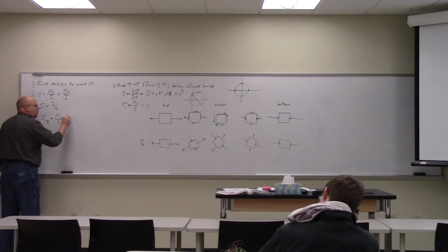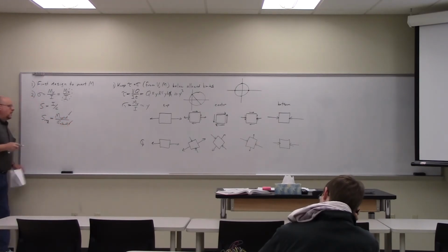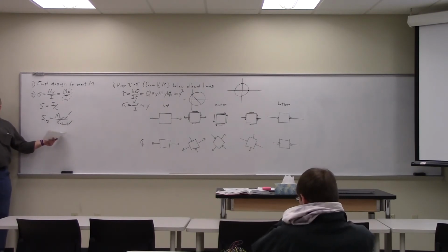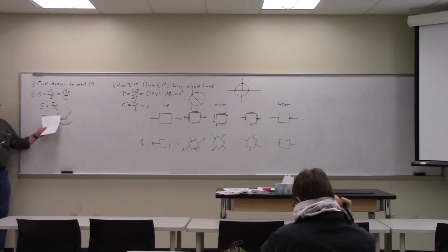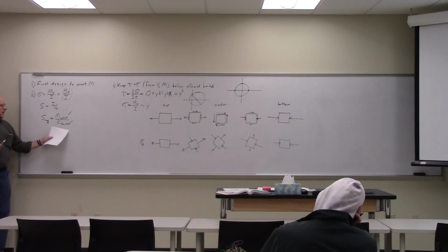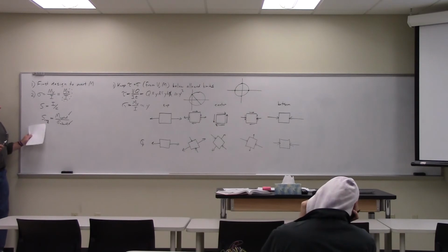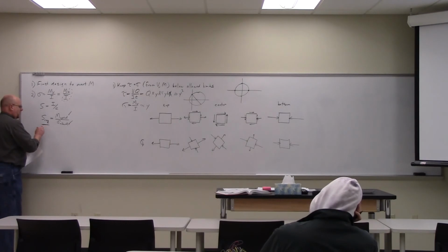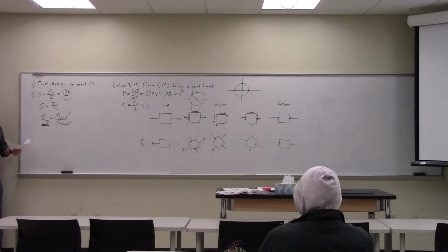Therefore, if I know what moment is applied and what material I'm using, the sigma allowed is going to be defined by the material. If it's steel, it's going to be bigger than if it's aluminum. If I know my applied moment based on my building design or whatever, and I know what material I'm using, then I've defined the required modulus of my beam. I need to go find a beam that has this required modulus. And this is what's going to be tabulated for beam designs, particular beam geometries.